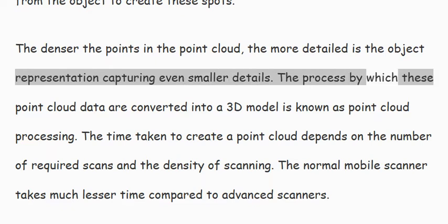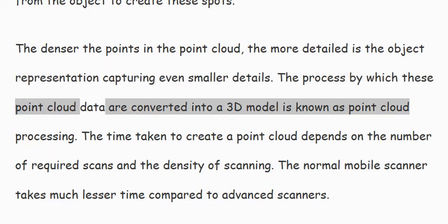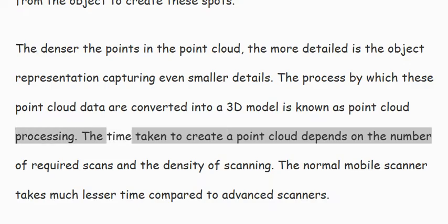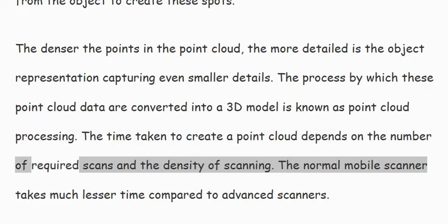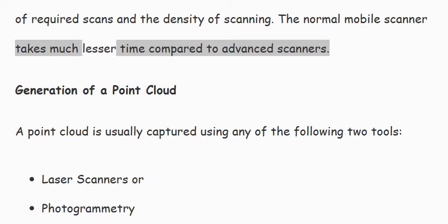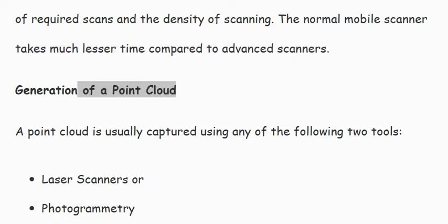The process by which these point cloud data are converted into a 3D model is known as point cloud processing. The time taken to create a point cloud depends on the number of required scans and the density of scanning. The normal mobile scanner takes much less time compared to advanced scanners. Generation of a point cloud.